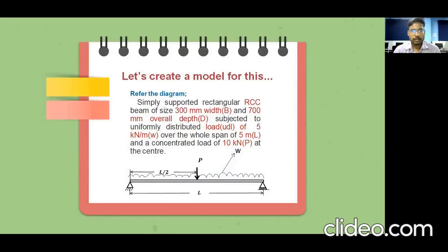So we have a problem. It is a simply supported rectangular RCC beam of size 300 mm width and 700 mm overall depth, subjected to uniformly distributed load of 5 kN per meter over the whole span of 5 meter. And there is also a concentrated load of 10 kN, which is acting at the center. So let's model this using the Staad Pro software.